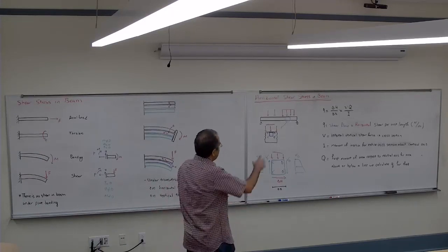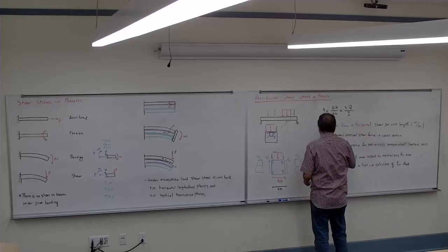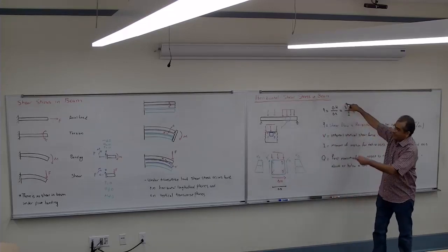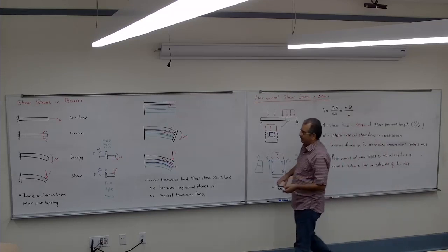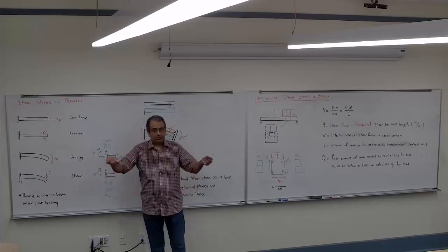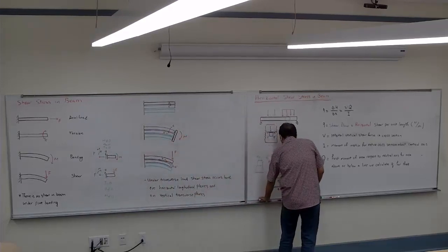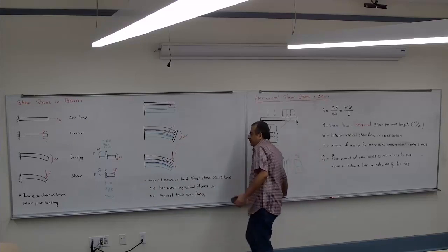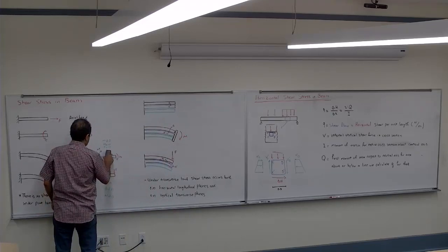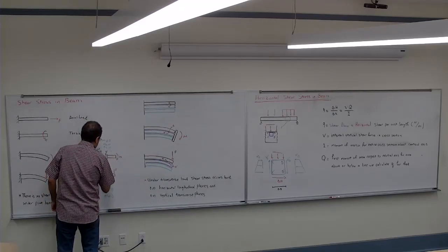So in that equation, the internal vertical force you already know how to calculate. We did it many times. You draw the shear diagram and find the shear at the cross section that you're asked about. We have done that many times in statics.